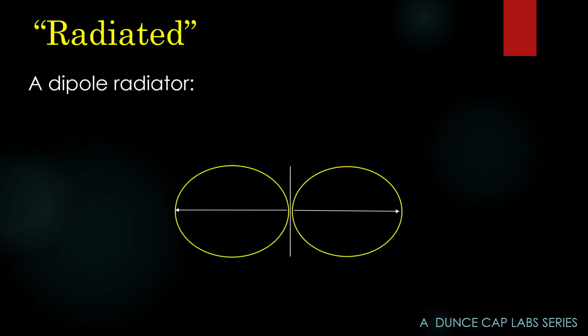Let's look at a dipole. The dipole, this one, is hung vertically. So here's the sky, here's the ground, and here's the horizon along this line. Now, as you can see, the greatest amount of radiation is toward the horizon. If you drew an arc from here to here, it would be much shorter, telling you that the radiation in this direction is much weaker. There is no radiation to speak of up or down.